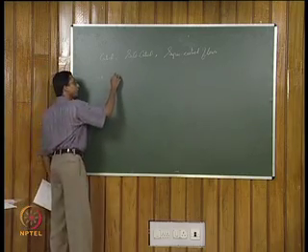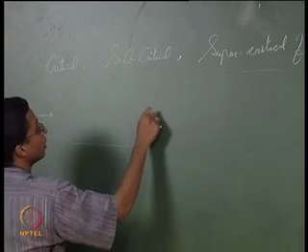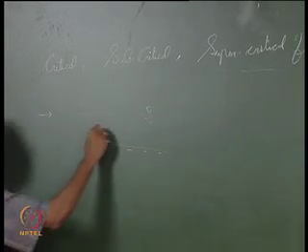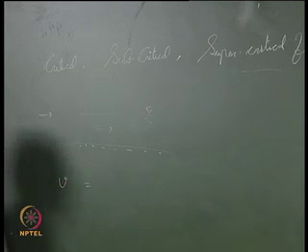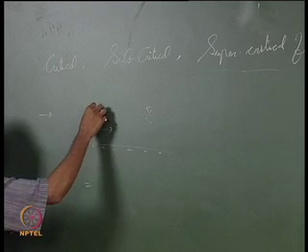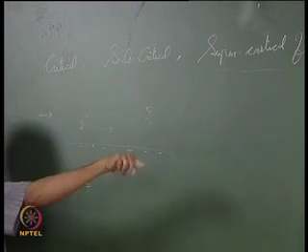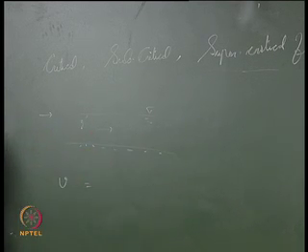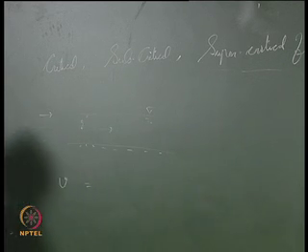If the velocity of the flow in a channel is equivalent to the velocity of a small amplitude wave created in a water of depth y moving with acceleration due to gravity, then such type of flows are called critical flows.